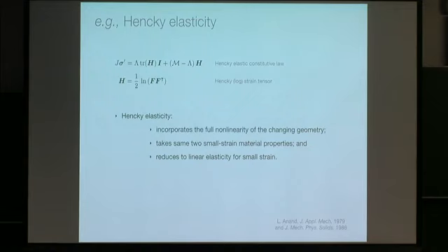It is logarithmic in particular, which apparently reflects better what real materials do under, say, moderate deformation, so tens of percent of strain, whereas linear elasticity is really only good in most materials up to fractions of a percent of strain.